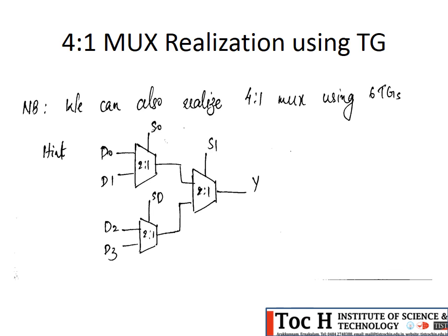The disadvantage of all these pass transistors is that they output a degraded logic level. To overcome that disadvantage, we went for the third logic, the transmission gate or C switch, which is a combination of P switch and N switch.